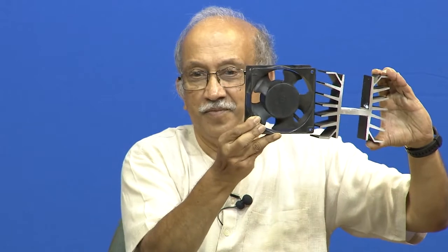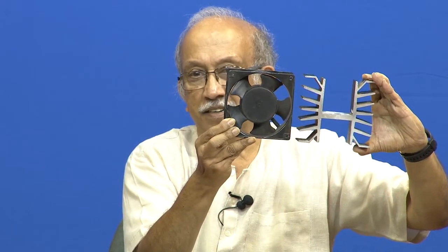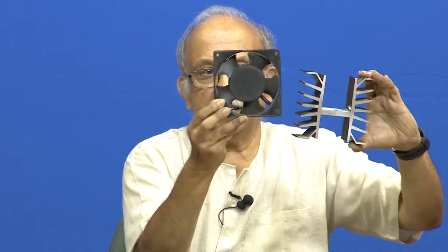Can you see? Have you noticed something? If you keep it in front of it, or in this case, let me keep it back of it. The fan has a particular flow pattern, and these fins have been made such that they directly follow the flow pattern. This is slightly different from the chip coolers which I have shown in the earlier pictures, which have radial flow. Seen that? If you go back to this fan, in the center portion there is not too much air flow.